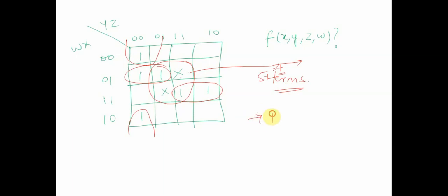The thing I wanted to show you is that don't cares can help us minimize the circuit. But do remember the precedence. The number one precedence should be having fewer product terms altogether, and the second is that the number of literals within a term should be fewer. So don't care is not helping us over here. If we had an example where a 1 was added over here and then there was an X, using don't care would have helped in such a case, because our first group would have been all corners, and then the X would have helped us create a don't care block.